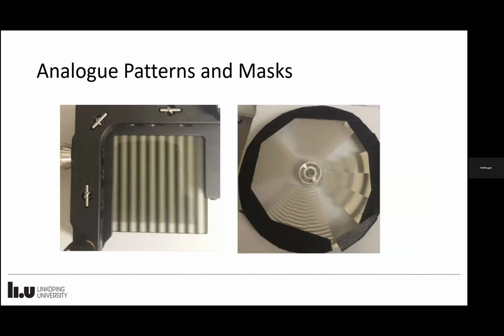Other people have done analog masks to go very fast, so you don't have to deal with the digital issues and stuff. So you can have a standard mask, you can have that shifted left and right to do the different phases, or you can just do a single snapshot approach where you presume a spatial frequency and do fitting to get the amplitude out of that.